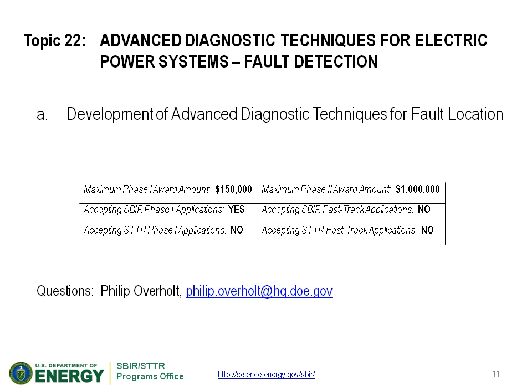We're looking for some type of technology that can be deployed and is in operation essentially full time, so that it can detect partial discharges and also detect actual faults, flashovers, so that it can record the location of the flashover or the partial discharge, and in the partial discharge case can detect it early on, so that action can be taken to detect what's actually going on.